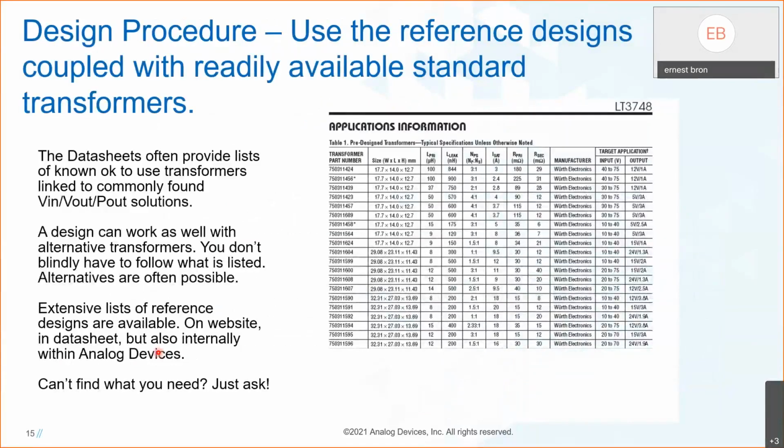So now that we've basically thrown away all the old flybacks and say, okay, if you want to do a flyback now, use this new methodology. The question is then, how do you design it, right? And the nice thing about these new parts is the design procedure actually is a lot simpler as well, because the whole secondary side with the TL431 and whatever is all gone now, and we really don't need to worry about all of that anymore.